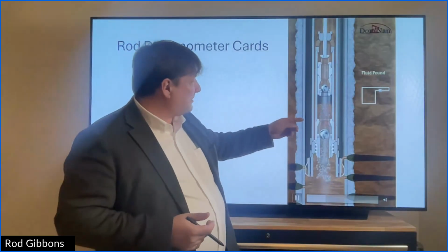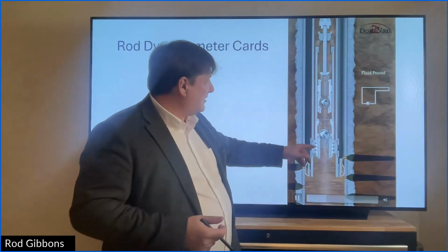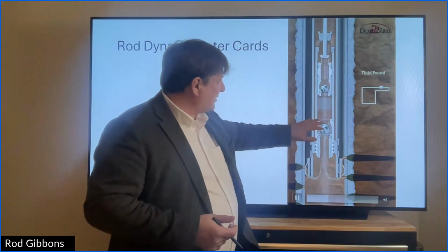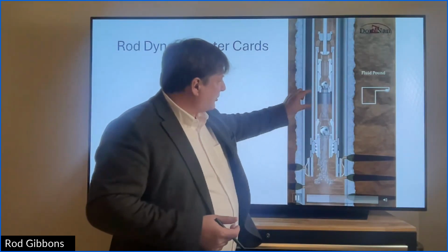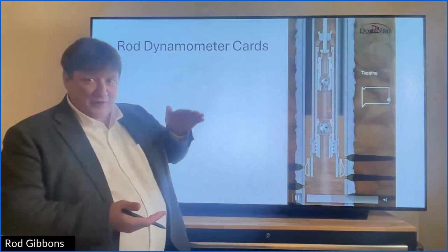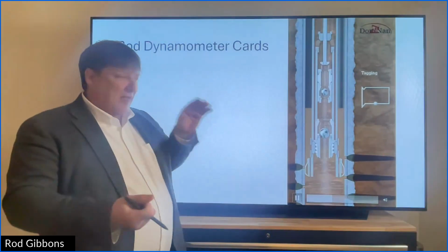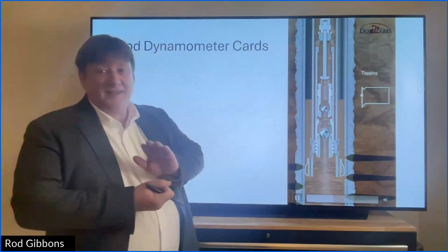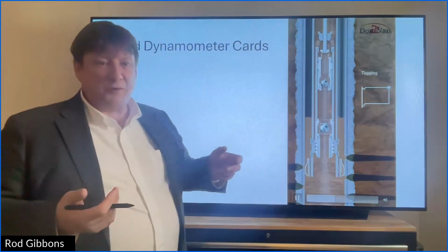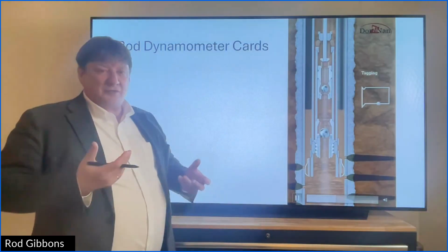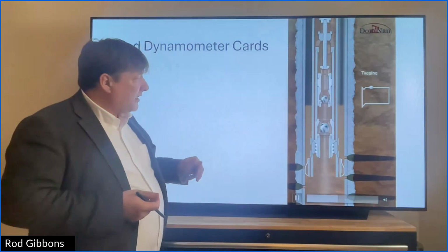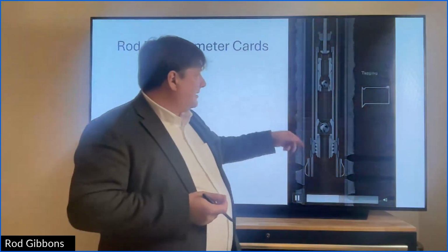Here's fluid pound. There's so much gas going in here that it's actually filling up. So you see the standing valves coming off. So now the gas is coming in, and gas is compressible. So now the pump jack is, say, halfway down its stroke, and then the ball hits the liquid, and that is what they call fluid pound, and that can cause you to damage the pump and have to have the pump changed out. This is tagging. There's another one, yeah.